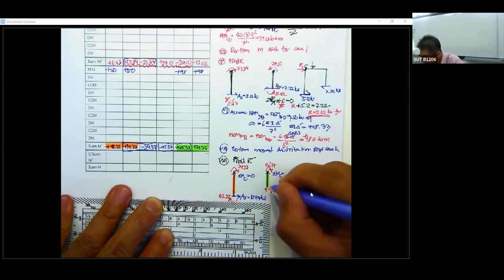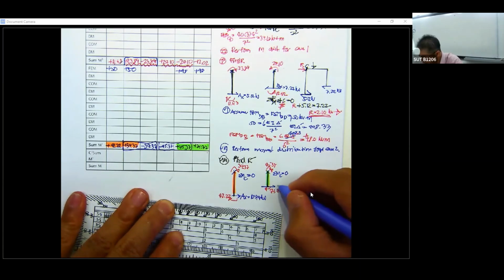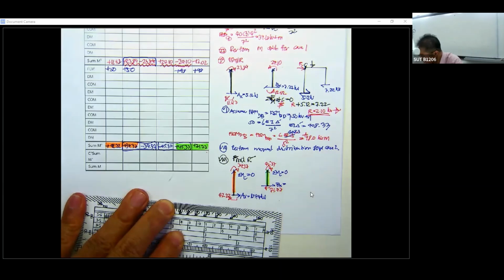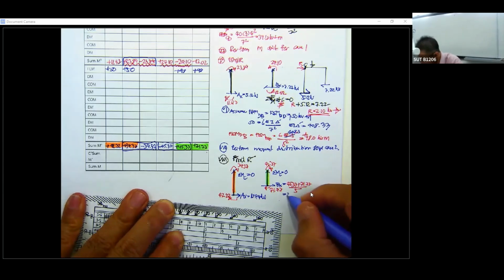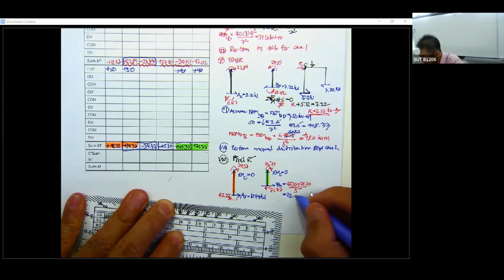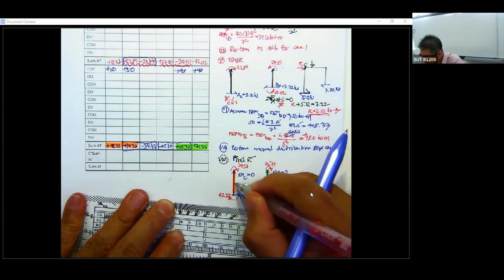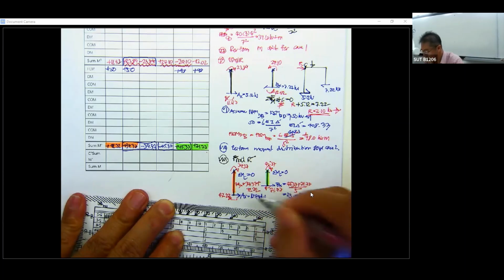And you do the same thing. Summation of the moment at C equal to 0. You will have what? This one B sub x equal to 45.37 plus 71.77 divided by 5. And then you get this one for 23.43 kilonewton. This one will come from take moment here. A sub x times 7 is going to be 34.37 plus 42.22, and then you get this.